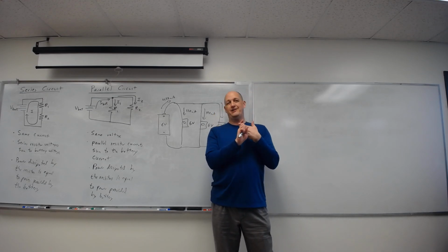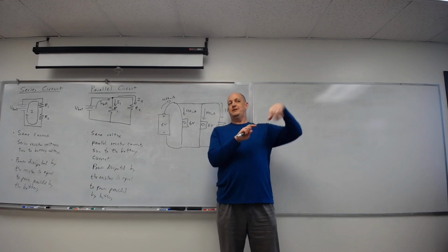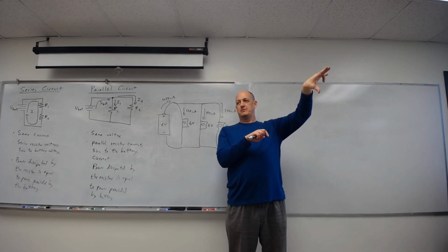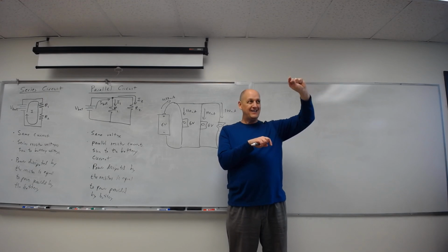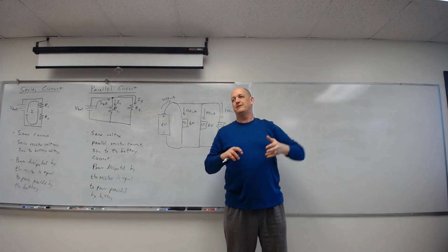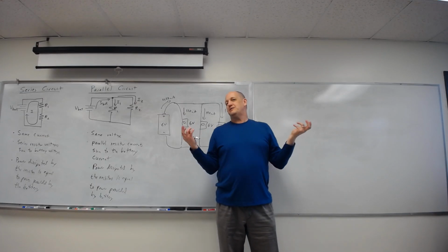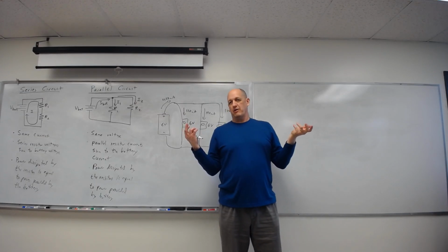And then I'll say calculate current. Calculated current: take your measured voltage, divide it by your measured resistance, and calculate it using Ohm's law. It should look almost the same as the measured. It should be a tiny little difference. Once you use Ohm's law so many times, it bakes into your brain.